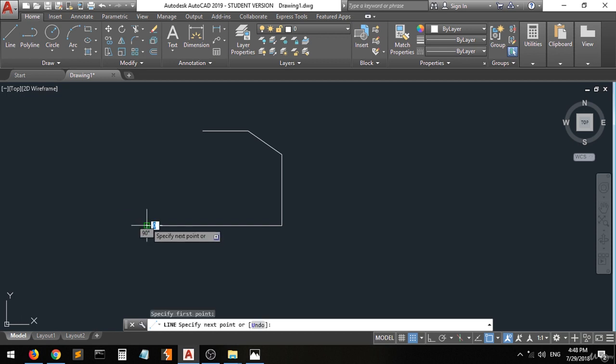So as we said, we will move 0.25 in the vertical direction. And again, you can use the coordinate entry, the relative coordinate entry, or the polar entry. Anything you think is easier. So I'll do it in the polar. At 0.25, since it's going in the positive direction, right? Then we'll do it at an angle of 90. And then we have this.